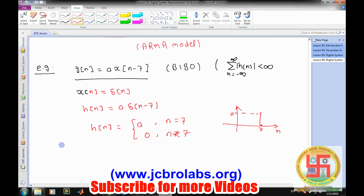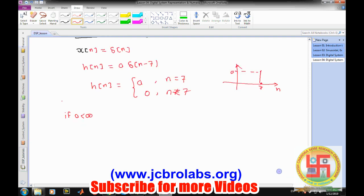Okay, so if a is less than infinity, because it was the bounded input signal, then obviously this signal is BIBO stable and its summation will be simply equal to a, which is always less than infinity. So this system is a BIBO stable system, or we can say this h of n is absolutely summable.